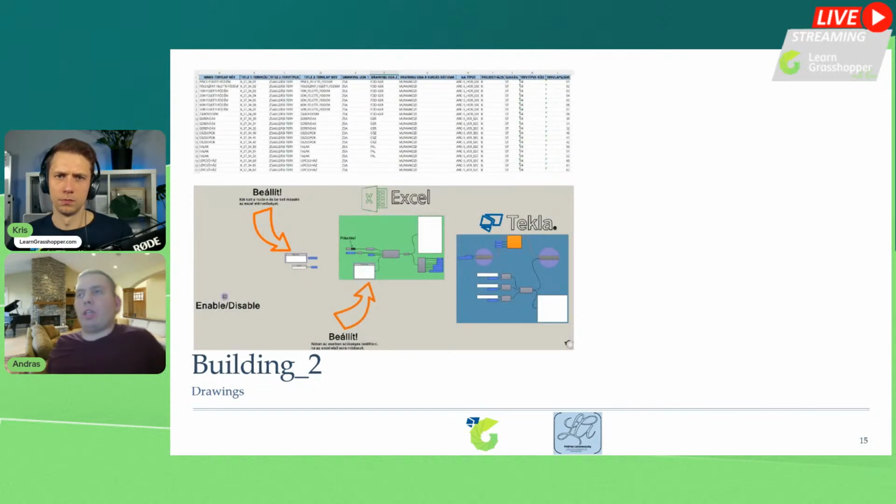The creation of the general arrangement drawing and filling in the drawing attributes is often done manually. With this image, I would like to illustrate that we can predefine the drawing attributes in Excel, and then read them using Grasshopper plugins or Python or C# code. Plugins, for example Lunchbox, and then generate the drawings with drawing link, so that the GA attributes will be filled in.